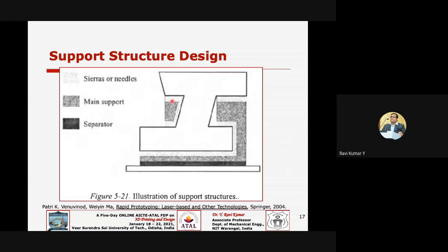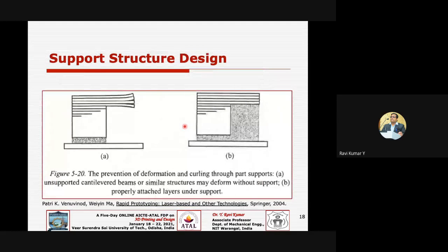In some cases it is an overhang, in some other case it may be an island, or a kind of internal feature. So accordingly, we need to vary the support styles. These are all design for 3D printing rules, or design rules. Only when one understands these aspects can you generate a sound build setup, or the codes for the 3D printing machine.